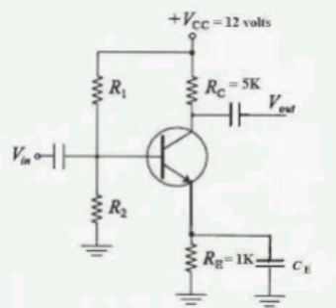Similarities between transformer and induction machine. Electromagnetic induction principle: both devices operate on the principle of electromagnetic induction. In a transformer, an alternating current in the primary winding creates a magnetic field that induces a voltage in the secondary winding. Similarly, in an induction machine, an AC current in the stator winding creates a rotating magnetic field that induces a current in the rotor.